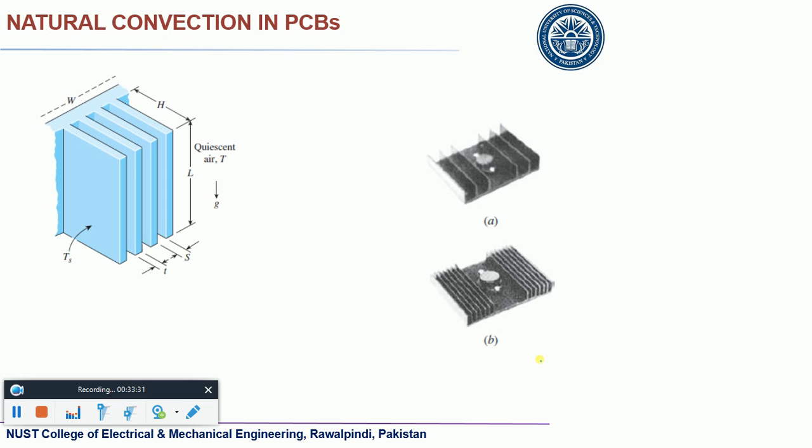Do you understand that? So you would have more friction, it means air velocities would be smaller. So you are increasing the area to enhance the heat transfer rate, but actually it is reducing the heat transfer rate. So what you need to do is go for some optimum configuration. Remember that. You have to go for some optimum configuration where you can deal with all of these things. Okay, so this is the application of all those correlations and all those theoretical things which we are going to study, right?